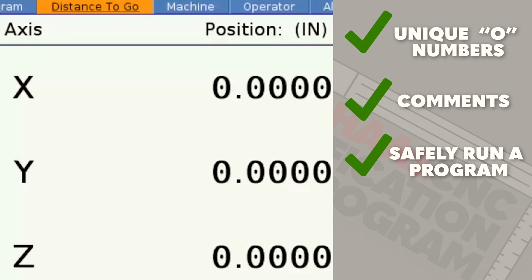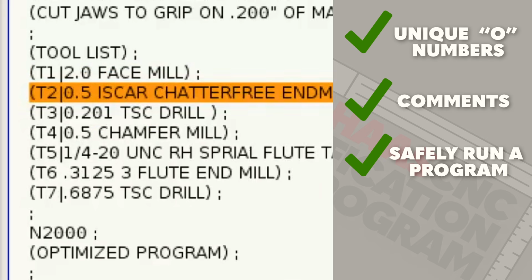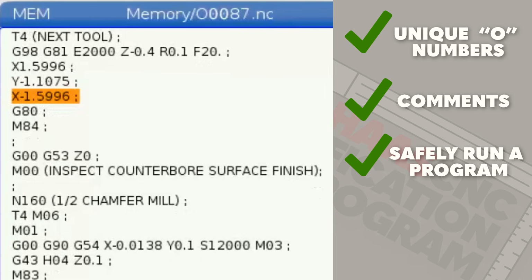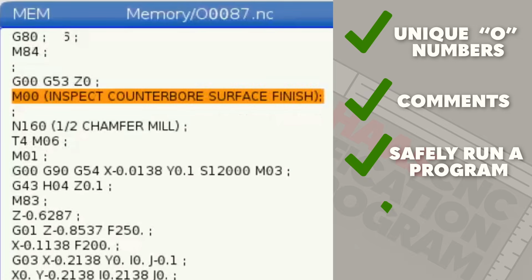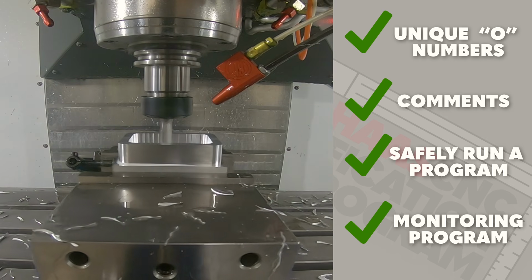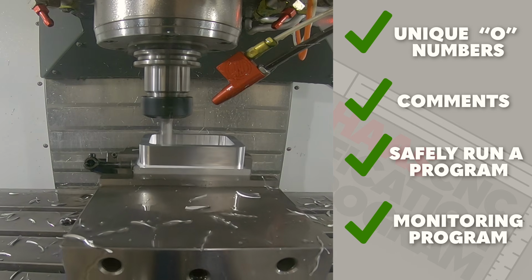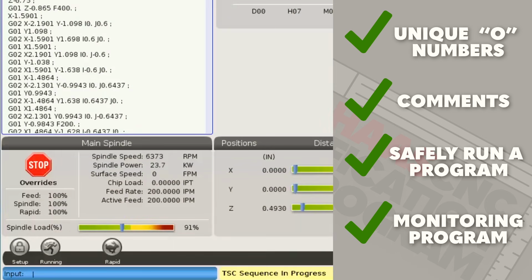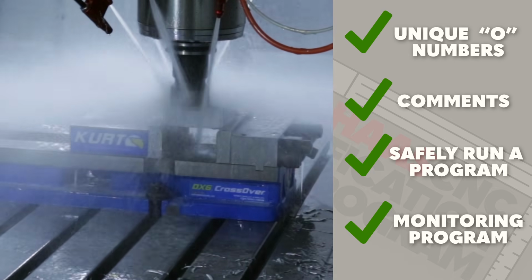We also learned how to identify tools and tool numbers, work offsets, and M00 program stop commands within a program. And finally, we learned to monitor how well our program is cutting by listening to the sound and feeling for vibration, monitoring spindle and axis load meters, and visually looking at surface finishes.